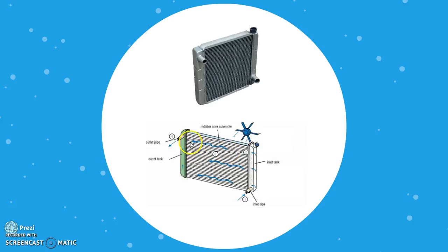And again, what happens is, this water will get collected into this outlet tank, and from this outlet pipe the water will come out, and again it is recirculated through the engine walls. So this is one kind of system in which the concepts of heat transfer are very useful. What size of these tubes to be selected, what should be the dimension of this system, all these things are decided on the basis of concepts of heat transfer.